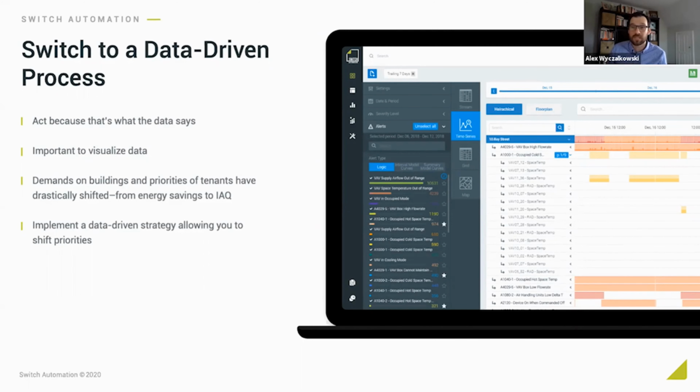So a very specific measure that you can take: let's say you do have CO2 sensors in your building, and you can monitor CO2, which is going to give you a sense of how many people are in the air, how much they're breathing in the air, releasing carbon dioxide. That's a metric that a lot of buildings will have. So before, we use CO2 for tenant comfort, and we may measure CO2 and say that 1,000 ppm, parts per million, is appropriate for tenant comfort. Well, we're maybe worried about building health.